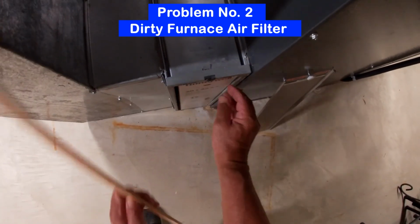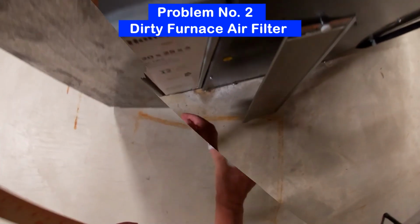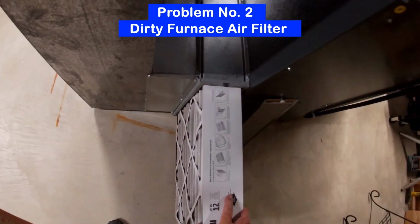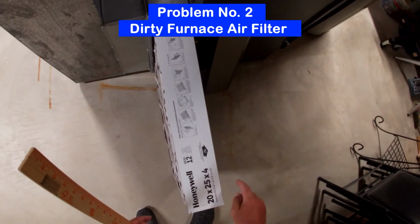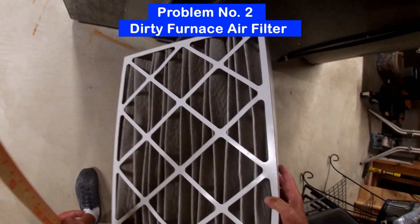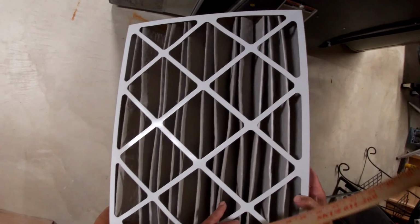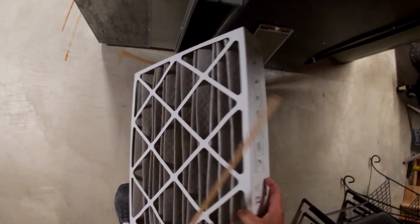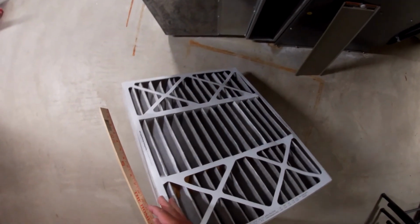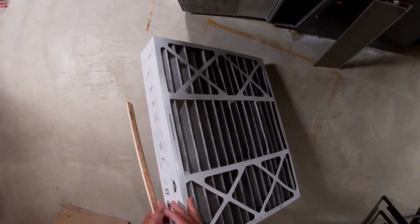Similar to a dirty and clogged condenser coil, a dirty furnace air filter can cause you major problems. It will also cause your air conditioner to run excessively to achieve the cooling level set on your thermostat and result in high electric bills and major wear and tear on your air conditioner, motor compressor, condenser fan motor, and heater fan motor, as well as your condenser capacitor and your furnace blower motor capacitor.